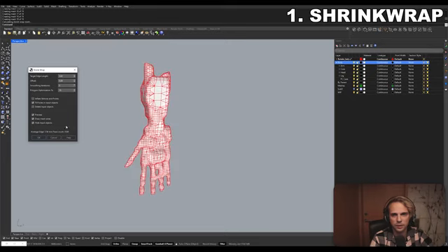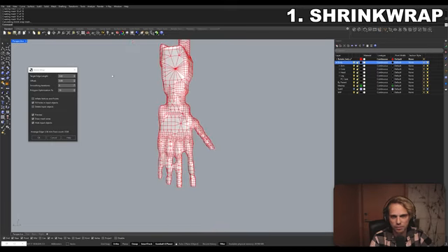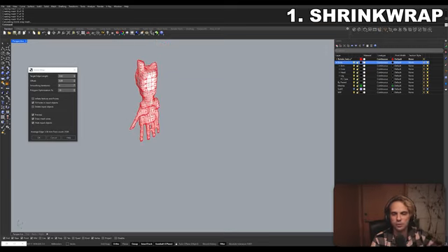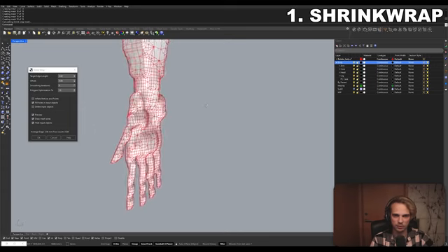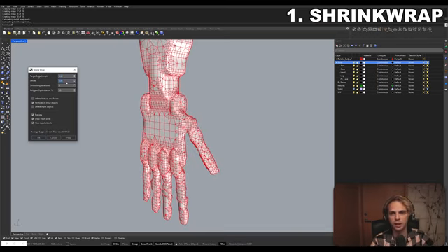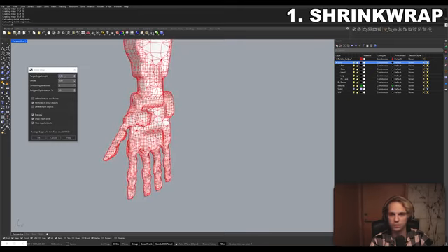Height input objects, and there is a mesh with this particular resolution, right? At this particular resolution wrapped around my hand. Does not look that great, right? Because the resolution is too high. So we're just going to tone it down a bit. So let's go for 2. Target edge length 2. Starts looking a little bit better.